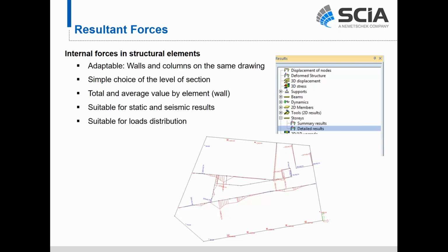And then obviously this also gives us information for load distribution. It gives us a good idea, when you have a rigid diaphragm or a semi-rigid diaphragm and you are applying lateral load, of how that lateral load is being taken by certain moment frames, certain concrete moment frames, or certain shear wall elements or shear wall cores, and how openings in the slab change that. And so that gives us a good way to look at the shear distribution or the load distribution through essentially a diaphragm in this case.